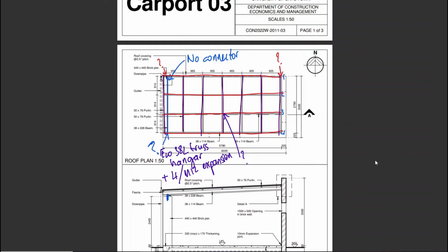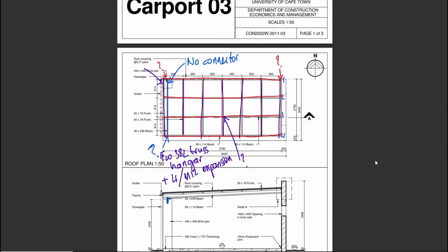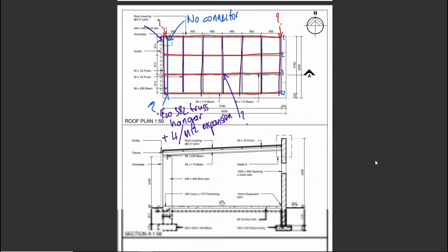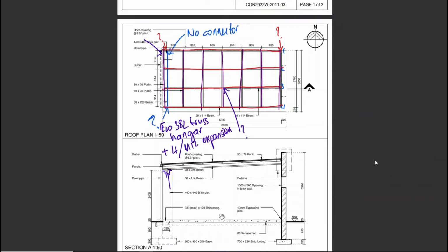Here, we have a main beam simply resting on a column. And what do you do here? Well, the answer is absolutely nothing. It's just resting there. They might bed the timber in brickwork, which is what looks like is happening here. It is bedded in the brickwork. You would have one course on that side, or one skin on either side, and probably mortar around it, just to hold it in place. That is the main beam.